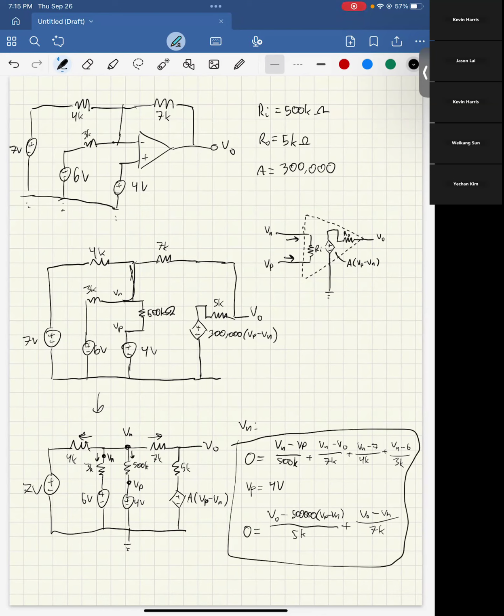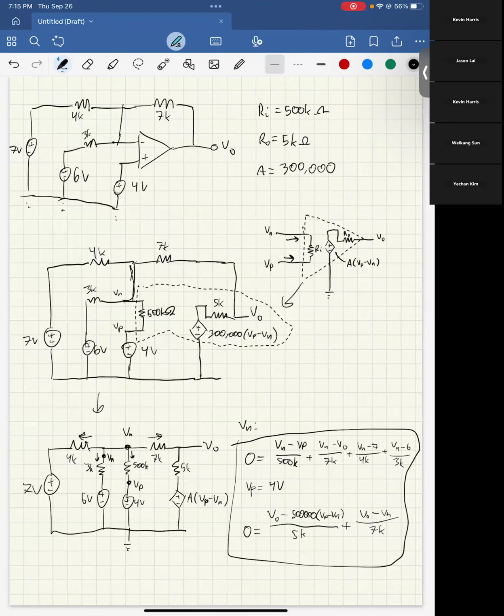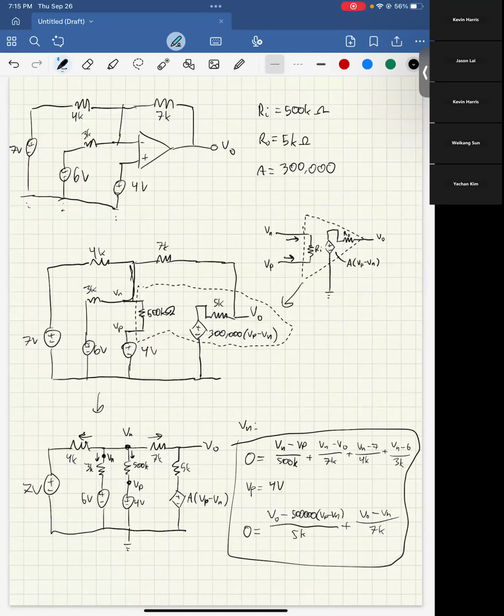This is the most you're going to have to do on a quiz. I know that took a while, but really all it was just applying this op-amp model. The op-amp is the stuff in this circle. If you do it really nicely on a quiz, you can sometimes draw the triangle to perfectly match. But you apply the op-amp model, you redraw the circuit so that it makes more sense to you, and then you'd write the equations just as if it was any circuit you found on any question.